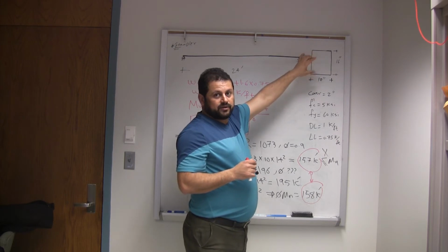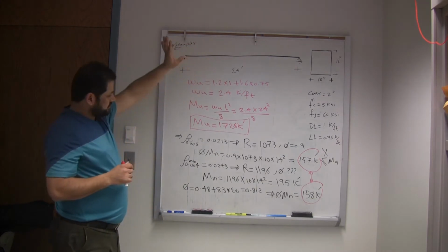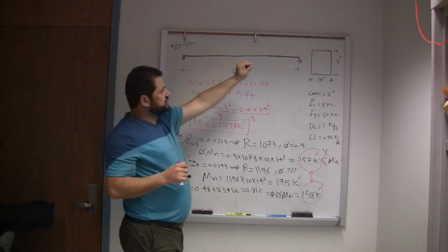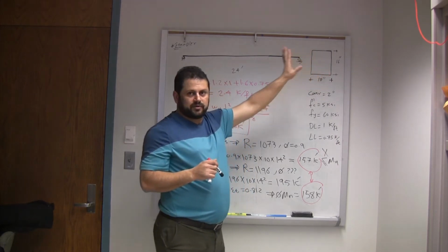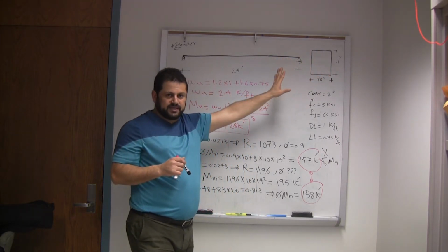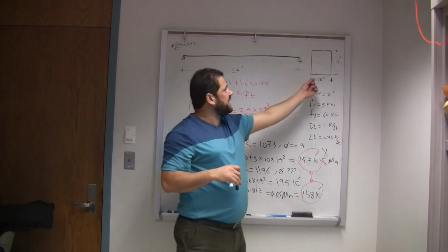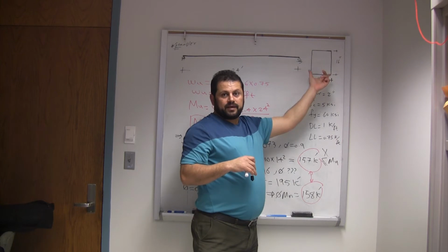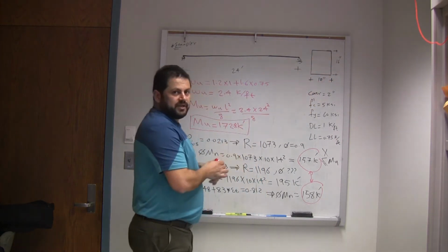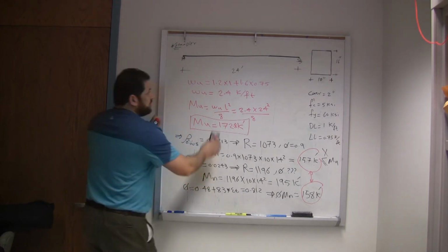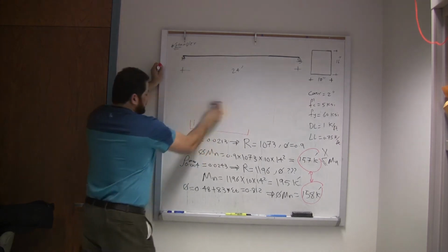So if we are flexible to change the width a little bit, I don't want to solve this one as doubly reinforced, because the reason behind solving this one is the deflection calculation. So I'm going to change my assumption, that I can change B. I'm not allowed to change the depth. I can change the width. Let's see how much B will help me so that the design will be okay. I don't have to design this one as doubly reinforced.